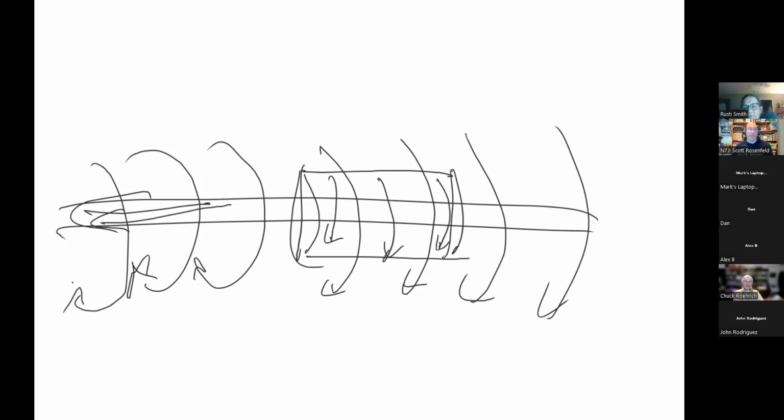In fact, virtually every switching supply cord will have it, because switching supplies operate at very high frequencies, like 30 or 40 or 50 kilohertz. And so, in order to keep from radiating a lot of energy, most switching power supplies, which are most DC power supplies now, will actually have a ferrite choke.